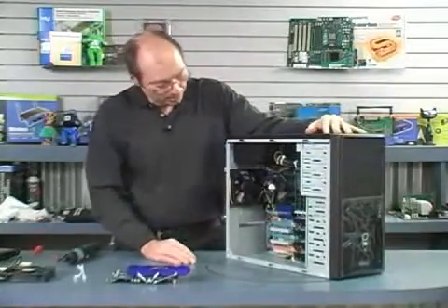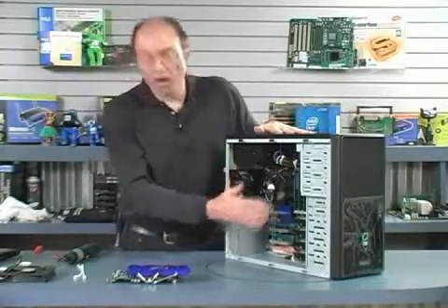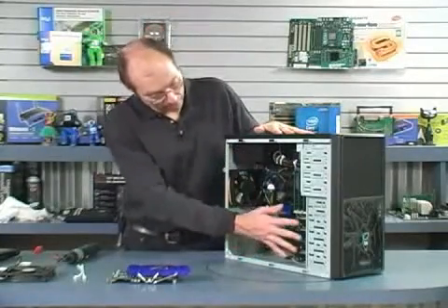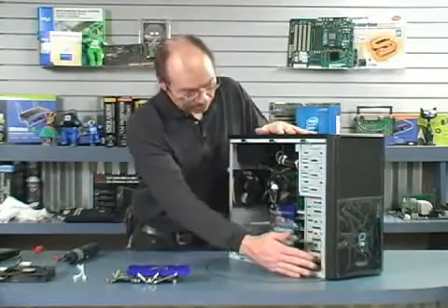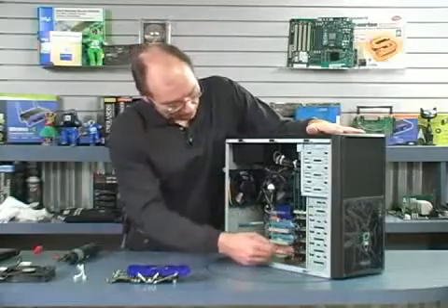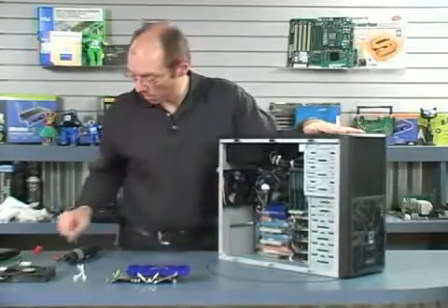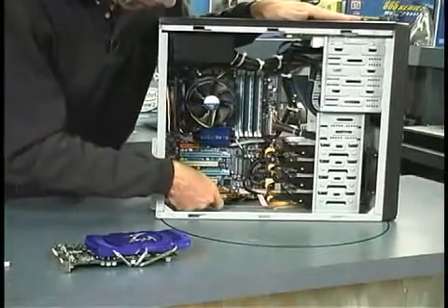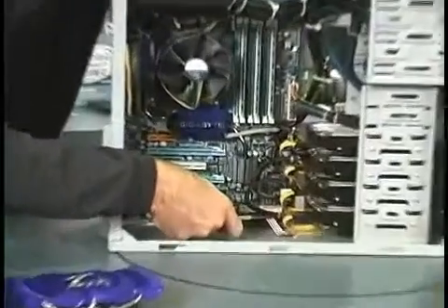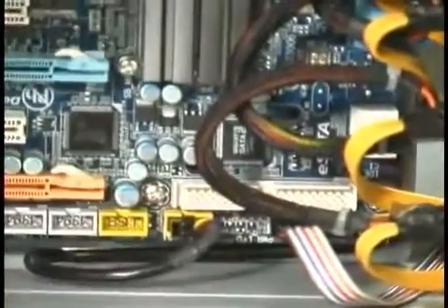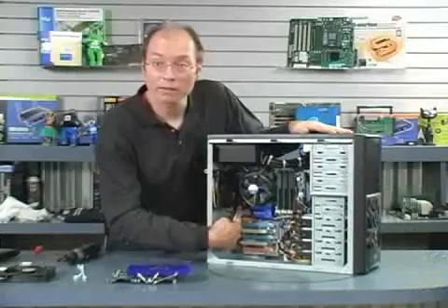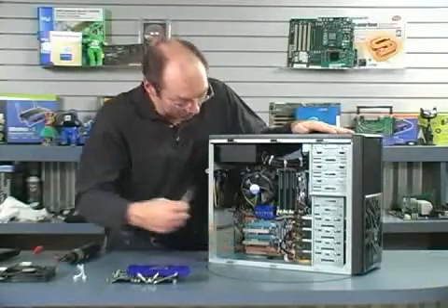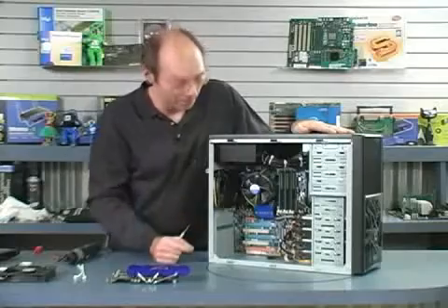Okay, there. At this point, I've connected all of the power to all of the disk drives, including the hard drives and the optical drive. I snapped the front cover plate back on the system and ran the front panel, USB, and audio connectors to the motherboard. You can see those here. Here's the USB connection, the front panel connection. Now that was made a whole lot easier because I had replaced those multiple little pin connectors with a single individual connector. The USB was a single individual connector, and the front panel audio was a single individual connector, not a bunch of little tiny pins that you had to try to get on there.